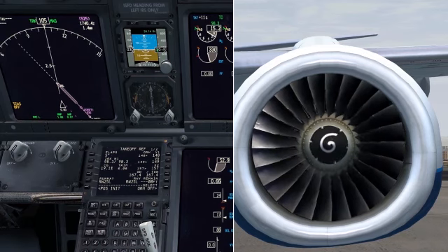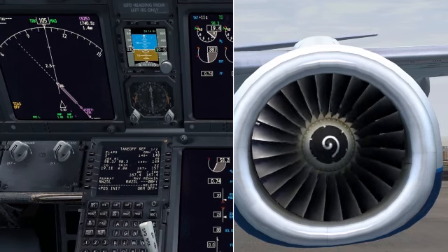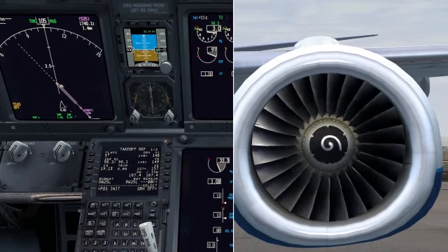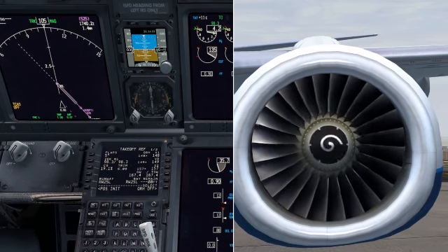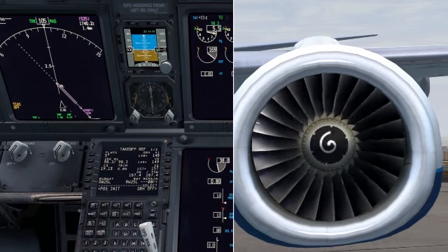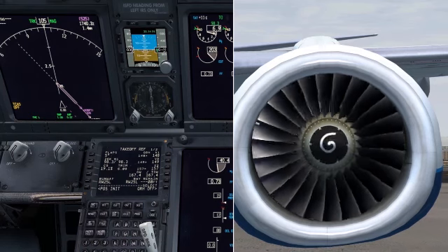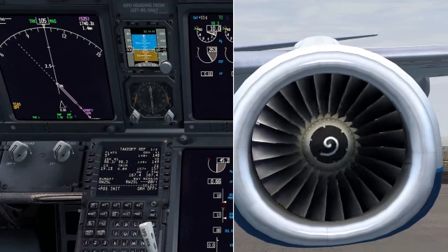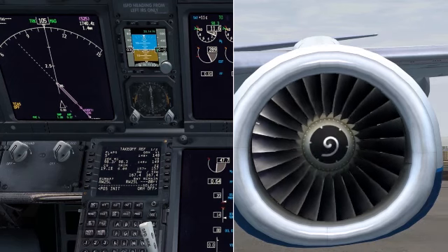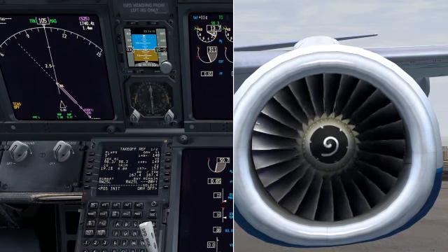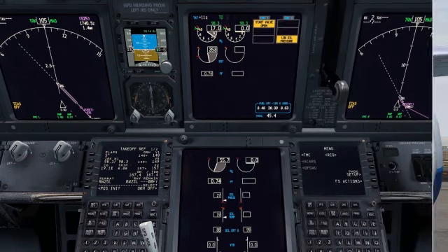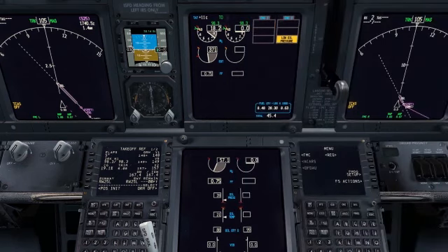The engine starter turns the engine N2 high-pressure shaft through the accessory gearbox we mentioned earlier. The engine starter manages to turn the N2 shaft by converting highly pressurized air into mechanical energy. This high-pressure compressed air is pneumatic power that is usable when the start valve opens. This air is provided by an engine start cart on the ground, an APU, or air pressure from another engine, assuming it's already running. As N2 revolutions per minute increase, all engine instruments must be monitored.